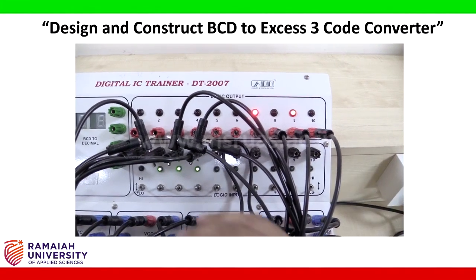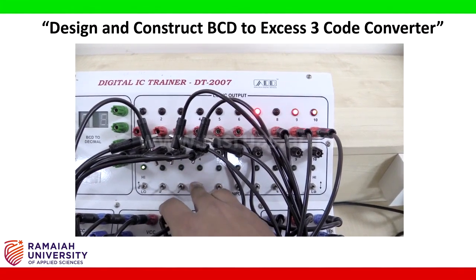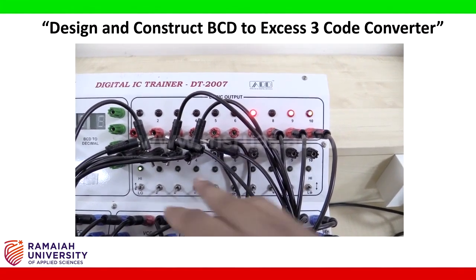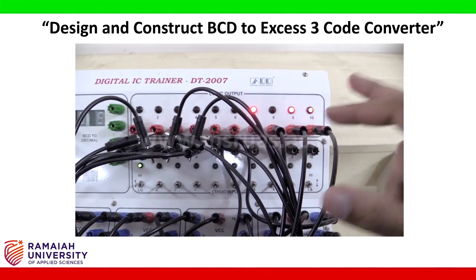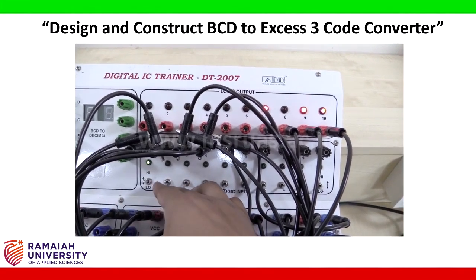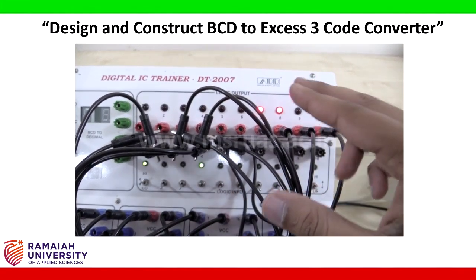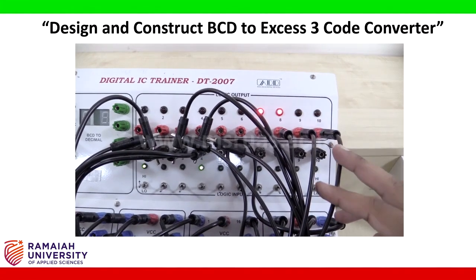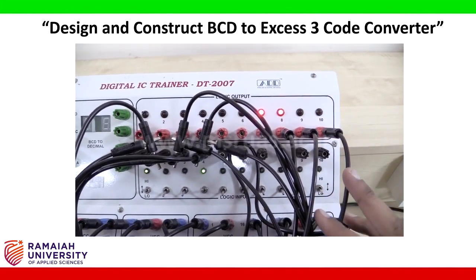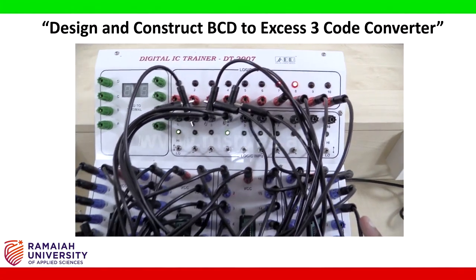Now next combination is 8, that is 1, 0, 0, 0. So now you can see the output is 1, 0, 1, 1. The last combination is 1, 0, 0, 1, and you can see the output is 1, 1, 0, 0. So this verifies the BCD to XS3 converter, and this completes the experiment.